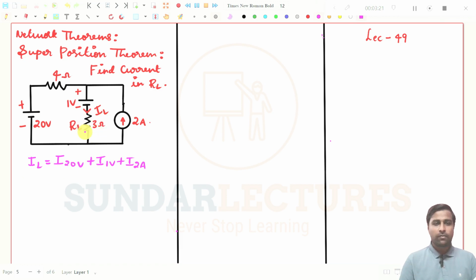If you want to find the current in this 3 ohm resistor, you just activate this 20 volt source and deactivate the 1 volt source and the 2 ampere source. Create that circuit and find the current in the 3 ohm resistance in this direction.